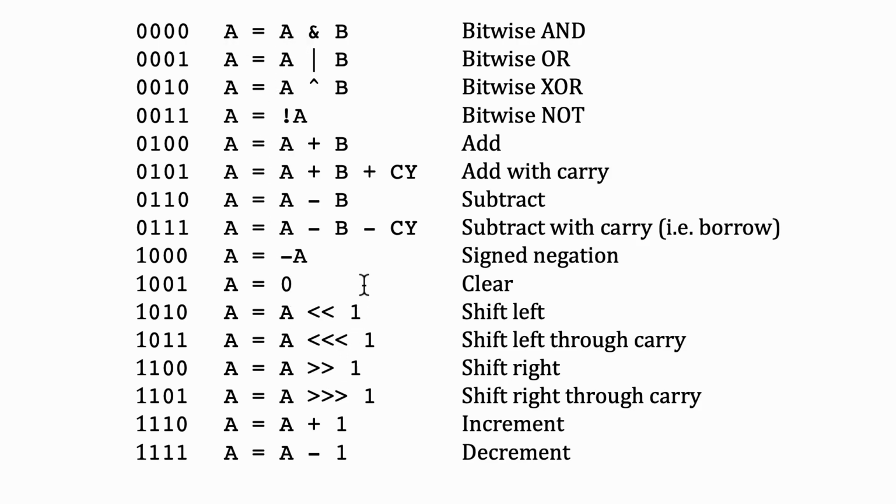All of these instructions will set all 4 of the condition codes so that after any one of these instructions we can use a conditional branch instruction. So we have 4 logical operations, AND, OR, exclusive OR, and the logical complement. And then we have an 8-bit addition instruction and an 8-bit subtraction instruction.